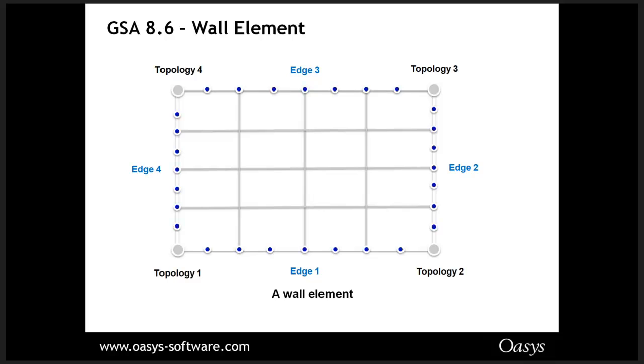So there are internal nodes and external nodes, because we mesh it. You will see there are internal nodes and external nodes. The internal nodes will be condensed off in the global analysis, and only the external nodes will be included in the global analysis. So that can make the global stiffness matrix smaller.